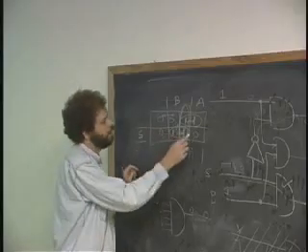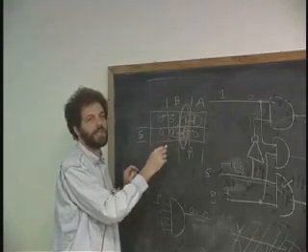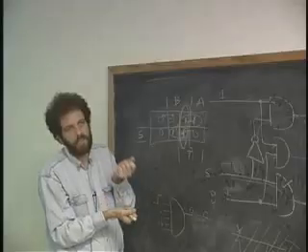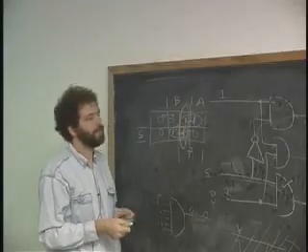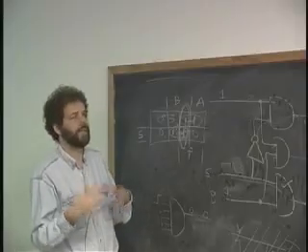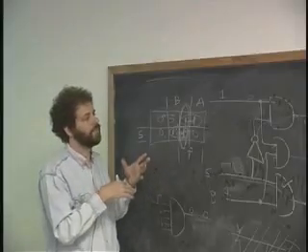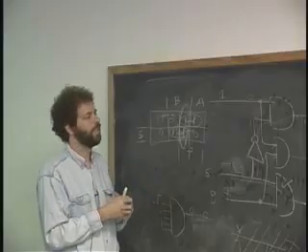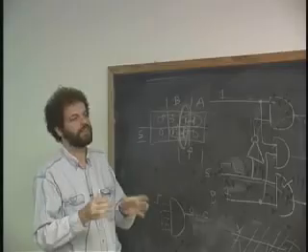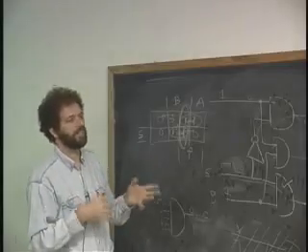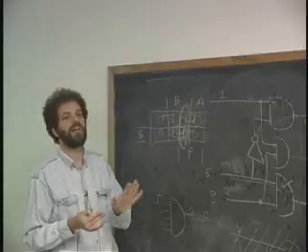For instance, when you go from here to here, there are 2 AND terms that turn on, and exactly what happens in the dynamics of the turn on and stuff like that. I could argue and probably convince you that that can't happen either, but I don't want to do it because it turns out 0 to 1 and 1 to 0 hazards are actually an ill-defined thing anyway. And it's the subject of a paper that I have half written, so I'm not going to bother to talk about it. They don't really matter.